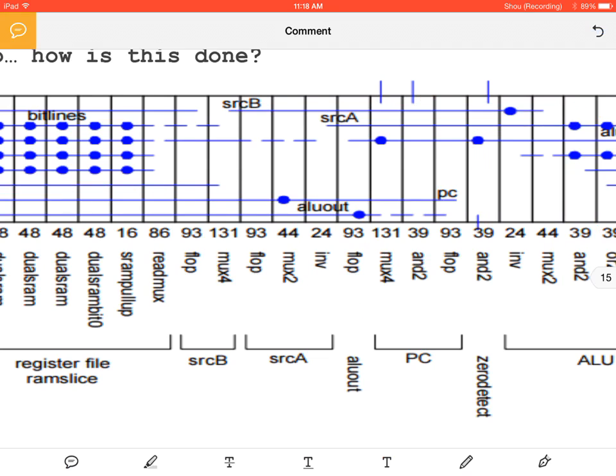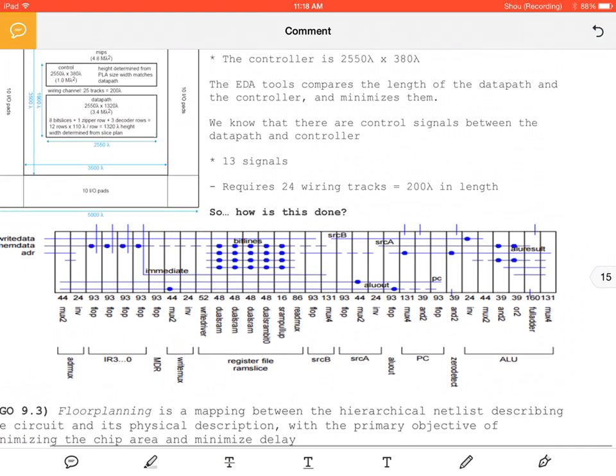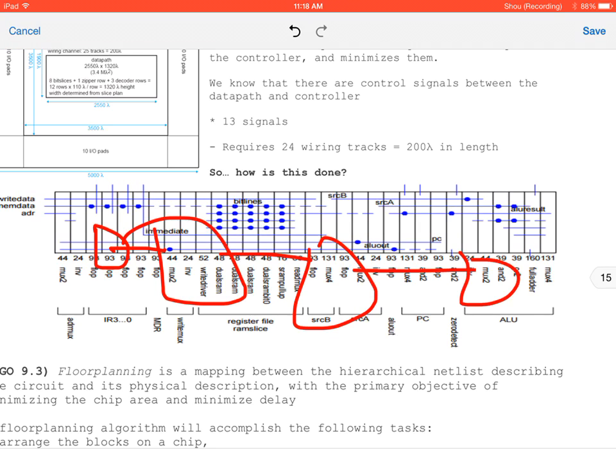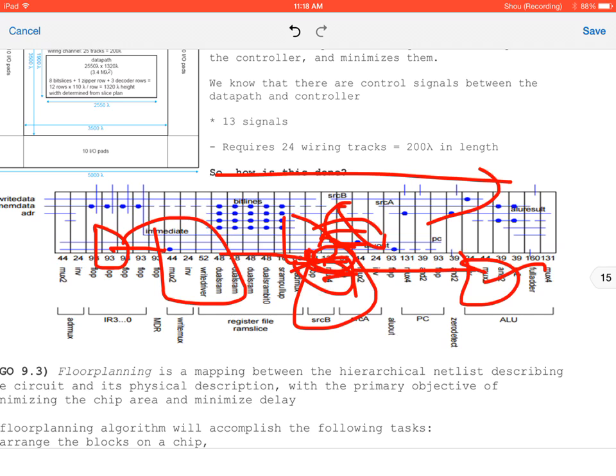And this layout is done in the floor plan for optimization. Even though we're drawing it out, we have the program counter, which goes to our memory, which goes to our register file and our ALU, because that's the data flow. That doesn't necessarily mean that that's how it's optimized. Let's say you can put your ALU here, and if you can minimize the wiring based on your capacitance driving, your parasitic capacitance, you can fit it into this kind of square area.